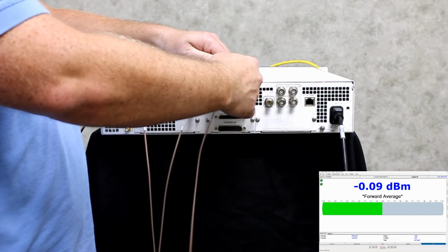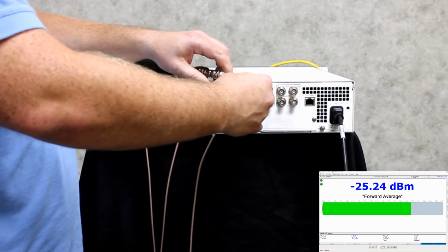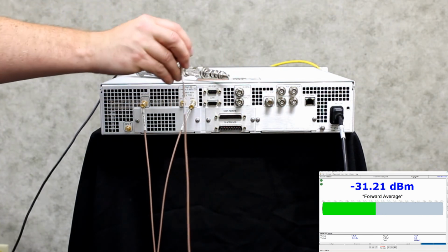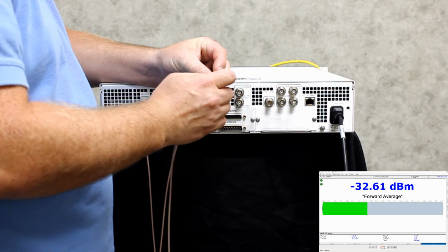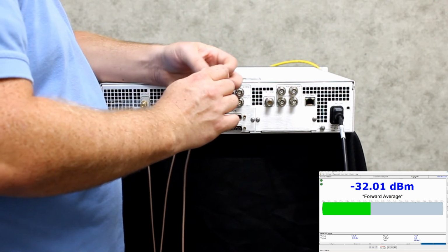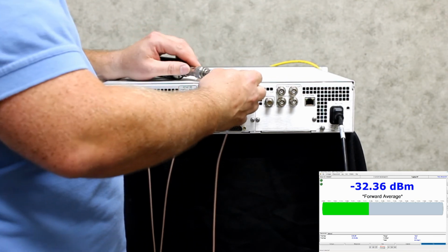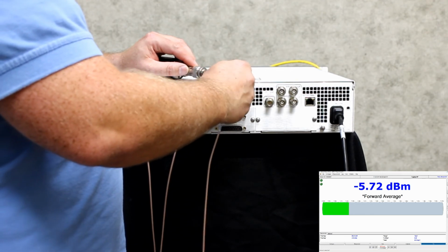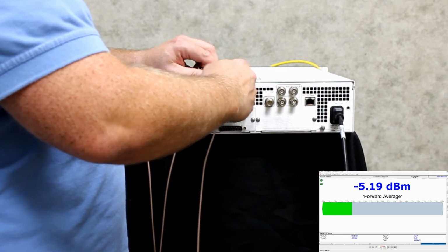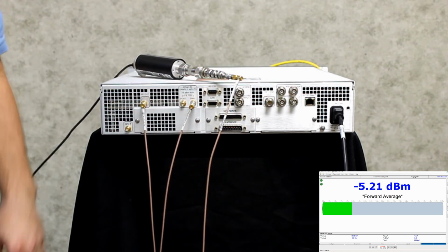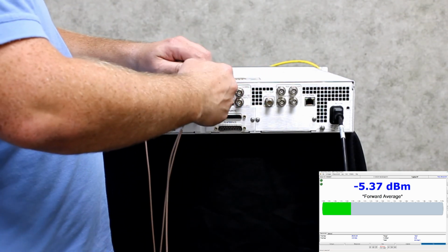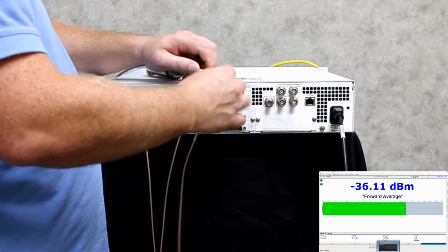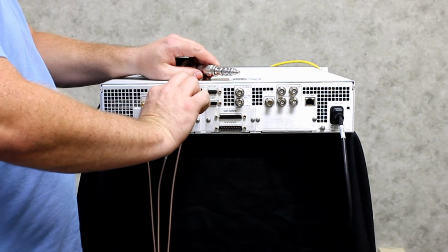So we're just going to get another 5 dB attenuator, and we're going to hook it up in series with the sample line and the power meter again, and remeasure it with the power meter. So we're just screwing in that RF attenuator now and hooking it up to the power meter. And as expected, we have a minus 5 dBm reading, which is perfect for what we're looking for. So now we can just remove the SMA pad and the cable and hook it back up to our exciter.